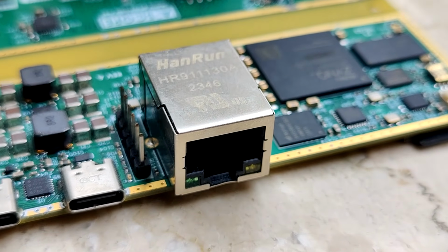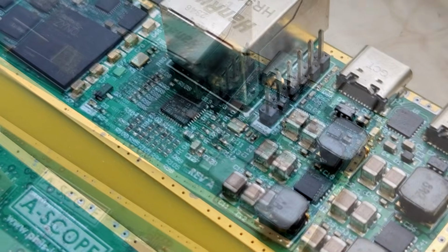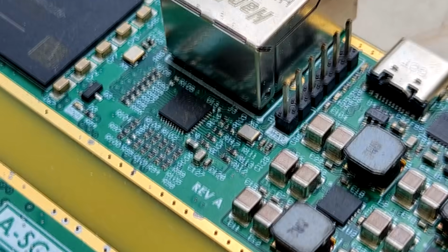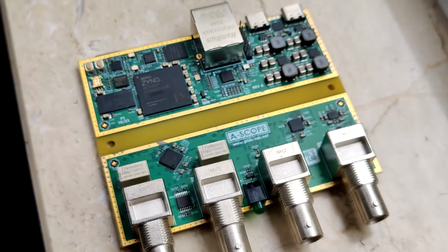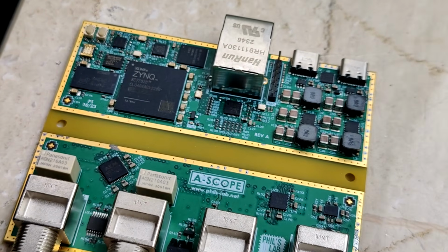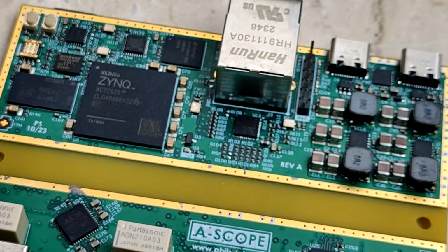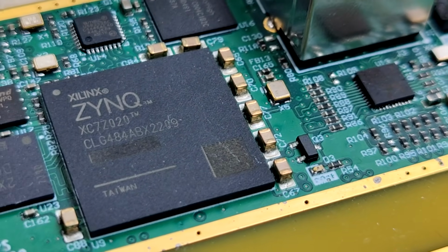We will be following this board along, looking also at the schematics, how everything is linked up and tied up, what we need to pay attention to, for example, strapping options, decoupling, and so on. And finally, we will be looking at the PCB design, looking at layout and routing, what we need to pay attention to, for instance, controlled impedance, delay matching, and general PCB design best practices when you are incorporating Gigabit Ethernet into your own PCB designs.